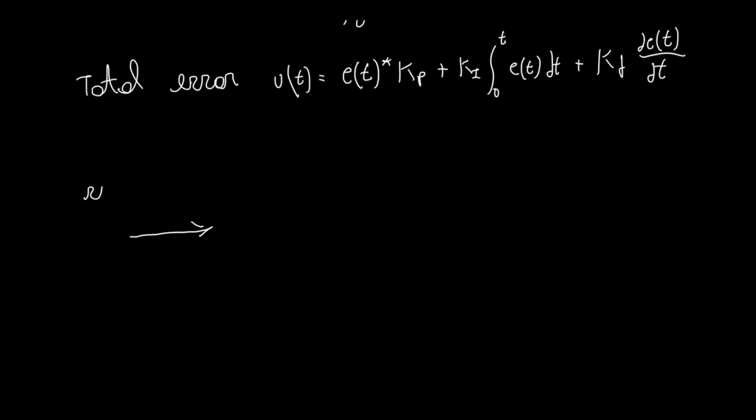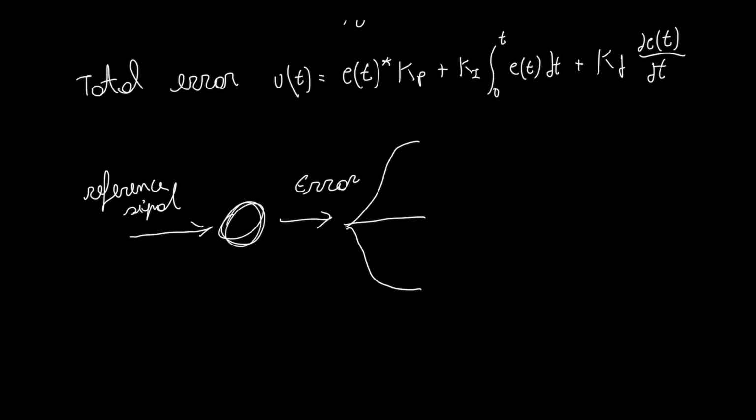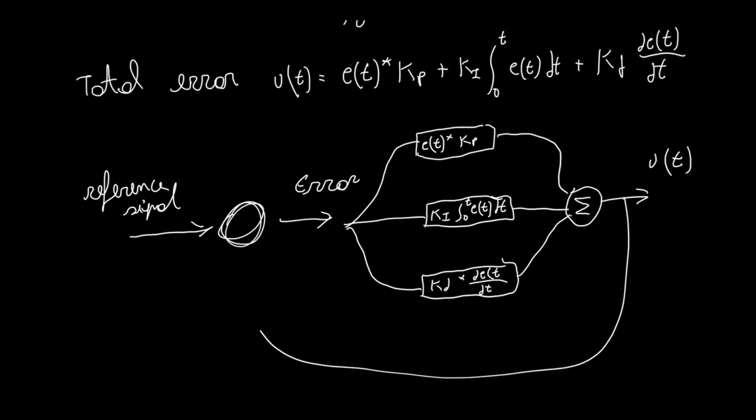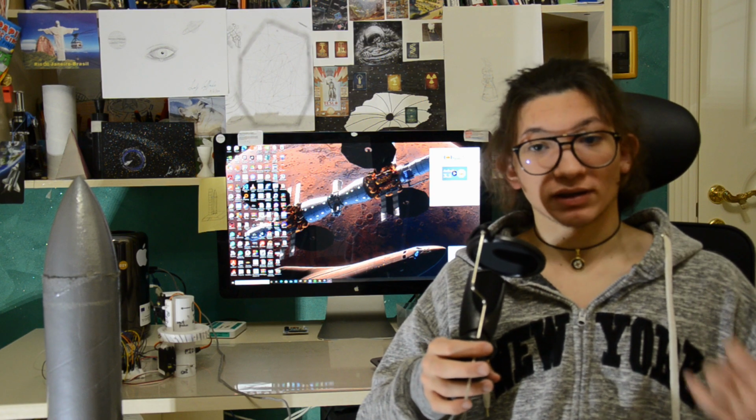Its output depends on the rate of change of the error with respect to time, multiplied by the derivative constant Kd. The PID controller is structured by the sum of all three control terms to then obtain the output, and then repeat the calculation in a loop for each input value in the time interval. In our case, the angles of the gyroscope.